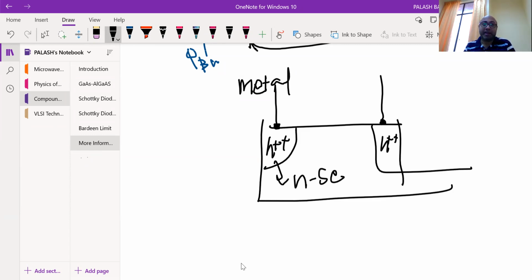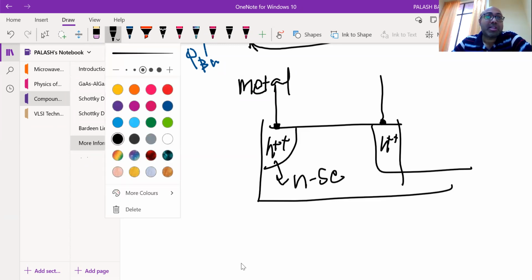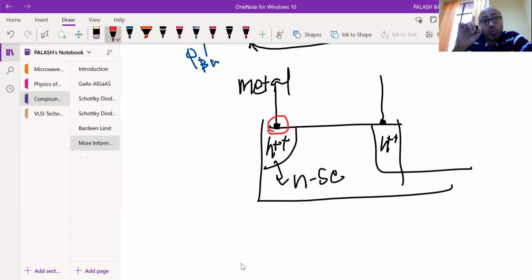If it is not doped heavily, you never get an ohmic contact, with low contact resistance. The moment you dope heavily, there won't be any contact resistance across this junction. Remember, this is one of the reasons why you are putting N++. Second reason is that you need to create a lot of electrons, like an electron tank. Whenever you need, this tank will supply electrons, so you need a lot of carriers across this zone. So it fulfills both cases. But the major thing is that it gives you ohmic contact, that is low resistance drop. To get this, people are doing N++, means higher doping.